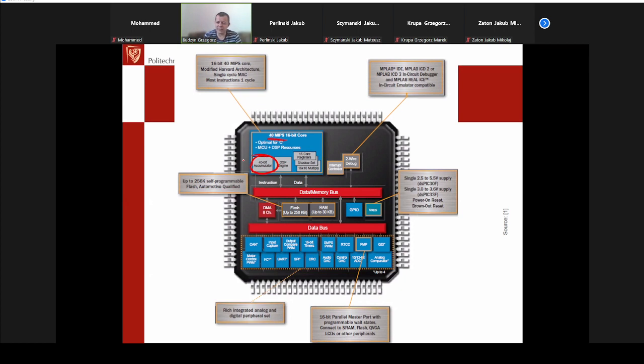Therefore, a wider accumulator really does the job, because then we can use a 16-bit coefficient multiplied by a 16-bit sample, and still we have 8 bits of space for adding numbers together, which means that in this particular example we can easily have more than 200 stages of the filter without sacrificing the fidelity, without the need to reduce the resolution before.